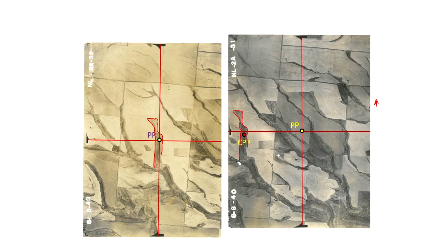Similarly, this will become a conjugate principal point here, and similarly you will need to transfer, and again this part of this landform has been seen here. Okay. So, if you can see this one here, this has been seen here. Okay. So, you transfer this over here, and that will give you the relative conjugate principal point. Now, having these 4 points will help you in identifying the line of flight. So you need to connect this. Okay. So you connect this. This will be a line of flight. Okay.